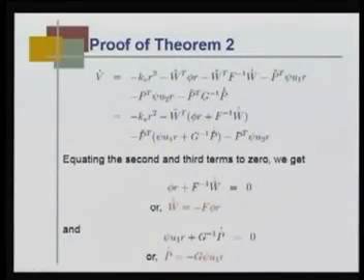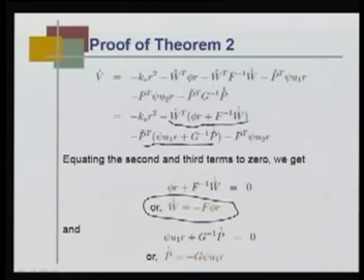If you recombine the derivative of the Lyapunov function, you get one combination here and one combination there. This is intelligently done so that we can find an update law for w hat dot and another update law for p hat dot, and make these two terms 0. That is done by these update terms, which are already there in the theorem.